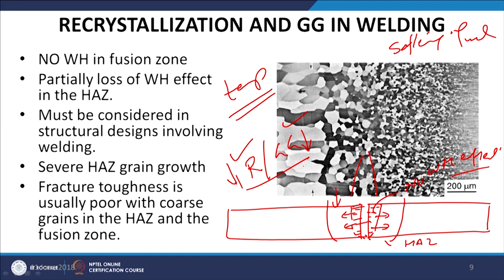And we know that whenever such kind of weld joint is made by the fusion welding process, it will be leading to the development of the heat affected zone or the weld zone which will be weaker, and these aspects must be considered in development of the suitable structural design. Not just the strength of the base metal is to be considered, but we need to consider the strength of the weld zone or the heat affected zone, whichever is weaker, for development of structural designs involving the welding.